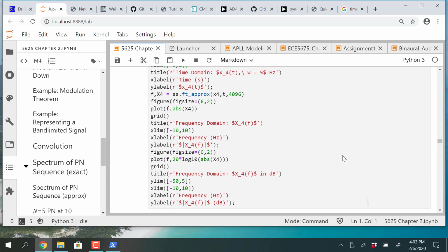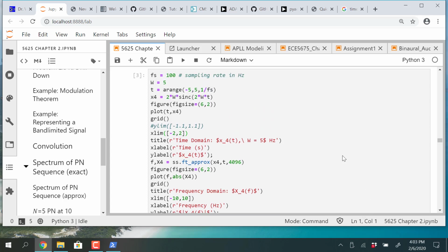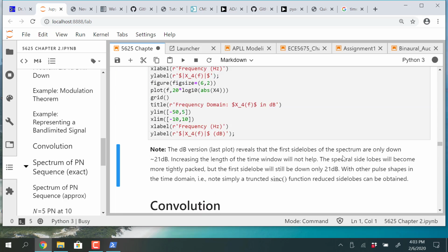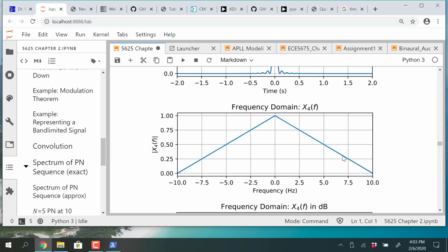This looks, well, okay, since I'm looking at this, how could I make this better? Well, I could actually, just notice if I make this squared, we know that sinc squared becomes what? Remember, we saw this last time. Sinc corresponds to rect, so this should be the triangle. Let's just play that out. There it is.